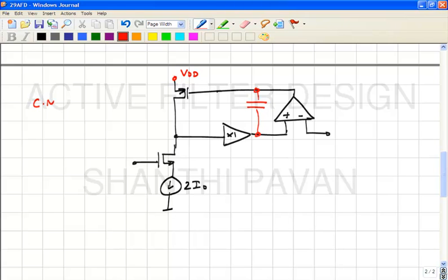This is the common mode equivalent circuit, and what we are doing is pumping a current here and looking at the output voltage here. Okay, so this is CC. Without CC, what happens? We all agree that there's one parasitic pole there because of that capacitance. There's another parasitic pole here as far as the common mode loop is concerned due to the integrating capacitance.